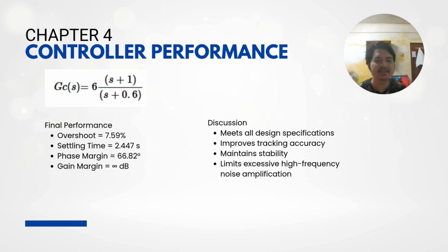So here you can see the compensator equation, and the designed lag compensator successfully satisfies all the required performance specifications. It improves tracking performance while maintaining adequate stability margins. Since a lag compensator has limited high frequency gain, it also reduces sensitivity to measurement noise compared with lead or PID controllers. Overall, the proposed controller provides a stable, reliable and robust solution to the VIGV actuation system.